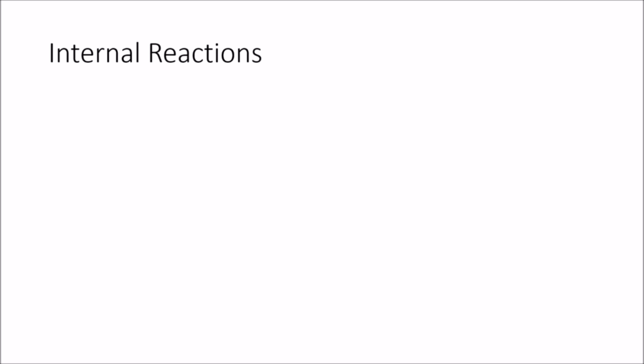Internal reactions is the basis of strengths of materials. Before you can learn about stresses, you need to be able to find the internal reactions, because the stress is determined by the internal reaction and the area that it is spread out across. What we are referring to when we say an internal reaction is what the material must feel at a specific point in order to properly withstand the force that is acting on the material.